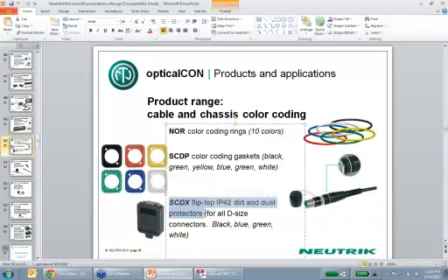There's a lot of fertilizer. There's a lot of possible corrosion of the connectors. Put these on there, flip them down when the connector's not in use, and it protects against a lot of that kind of corrosion. Again, I hate these gaskets because you should really only use blue or black for single mode or multi-mode, but then we offer these other color coding options. So I know I'm being a little inconsistent in how I talk about this, but the color coding options are nice.